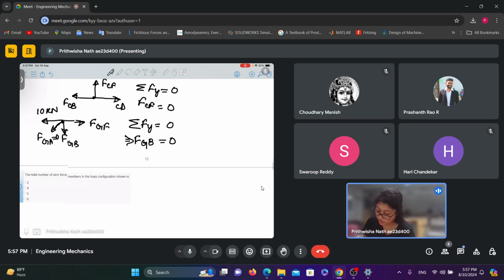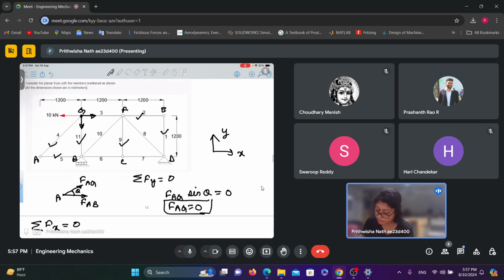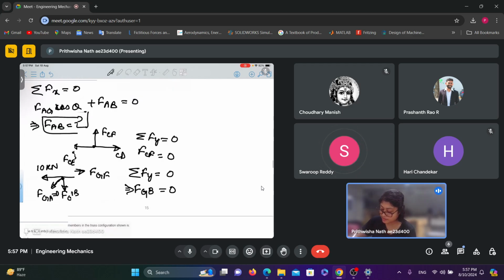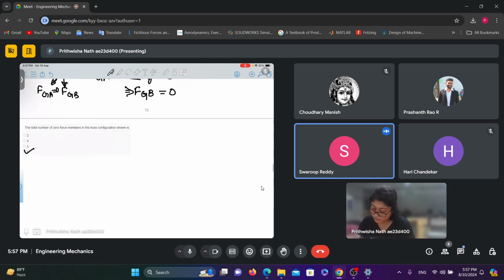So total number of zero force members. What are the zero force members here? 4, 5, 9, 1, 2 and 11. So 1, 2, 3, 4, 5, 6. 6 members as zero force members, right? So option 6 is correct. Is this clear to everyone? Yes, ma'am.